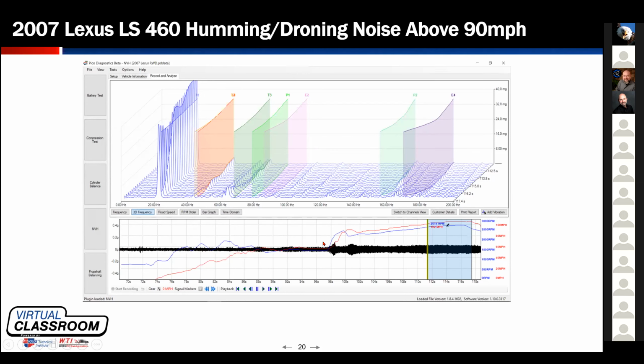And you can see that in blue, as I got to this line right here, I'm at 2,600 RPM. In red, I'm at 102 miles an hour. So I have a pretty substantial increase in speed. And from an amplitude, from a force standpoint, my force of vibration was flat, flat, flat, flat, nothing, nothing, nothing, nothing.